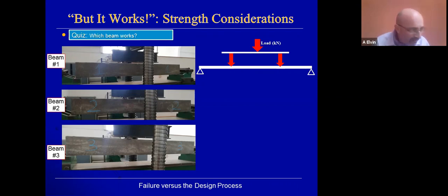Let me also let the cat a little bit out of the bag. All 3 beams have identical concrete that was mixed on the same day and are identically dimensioned. The length, the cross-section, and the loading is identical. What are the beam section properties? We'll talk about that in a second. My eyes have failed, obviously. Spans. The span is very small. The span is 1.5 meters.